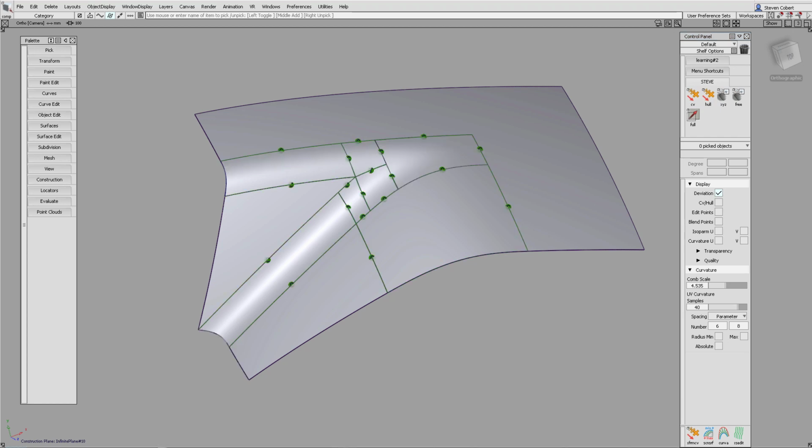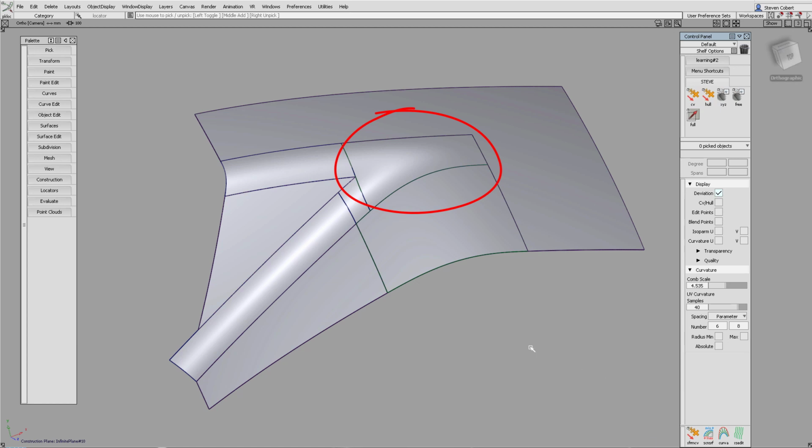This is what our final surface layout will look like. The end surface resolves the transition between the 2 fillets and the main block. The trick is in building this surface correctly. So the first step is to build a single surface which approximates the whole area. We'll then split this up so that we can align it into the fillets accurately. First of all, we're going to create a 4-sided hole.